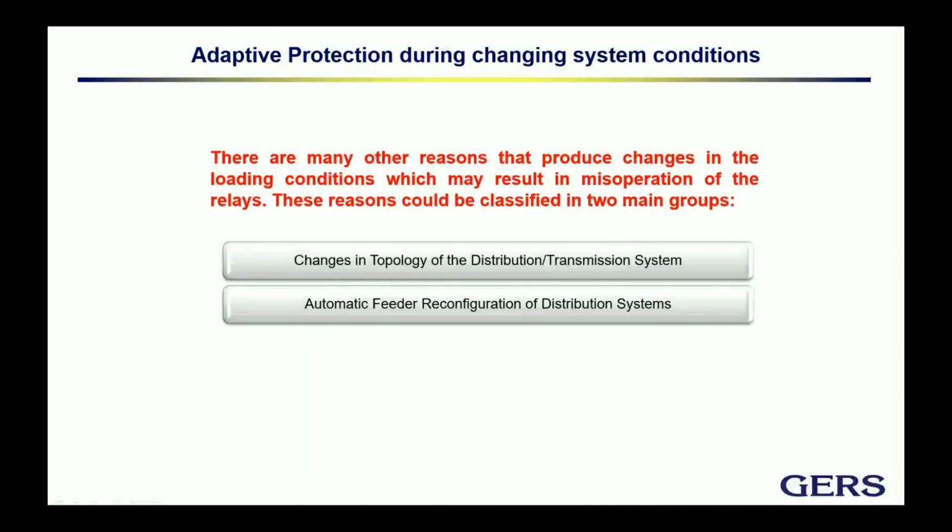So adaptive protection is exactly this. Adaptive protection is the technology that considers the possibility of the relays to readjust to the prevailing condition of the system once the operating conditions change. Why? For example, for this case, feeder reconfiguration, or because, say, a PV farm or a wind farm comes into service unexpectedly. I would say unexpectedly because wind farms can close in and out several times in the day, and solar facilities at least 2, early in the morning and early in the evening.